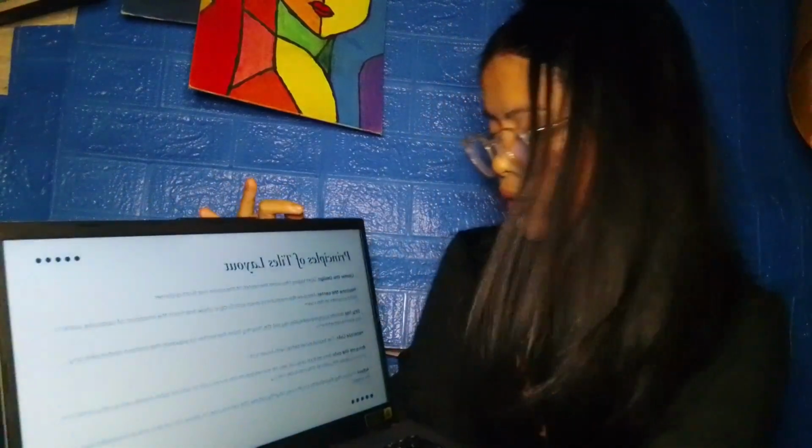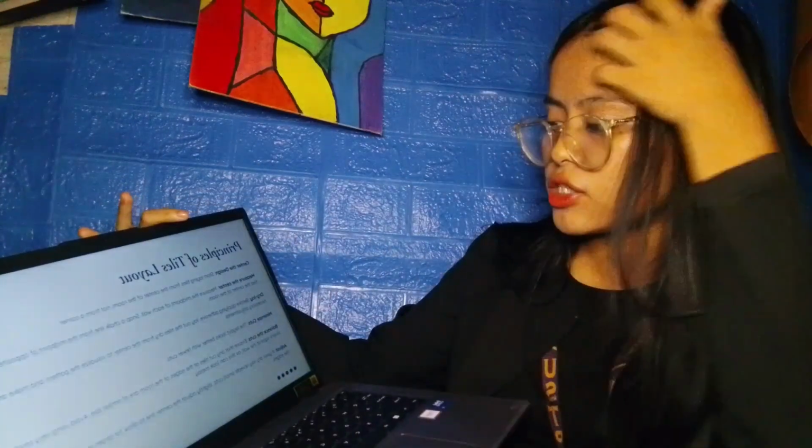And the last one, adjust. If your dry lay reveals small cuts, slightly adjust the center line to allow larger, more balanced tiles at the edges. So, again, we have the principles. Center the design. The second, measure the center. Dry lay. Minimize and balance the cuts and adjust.